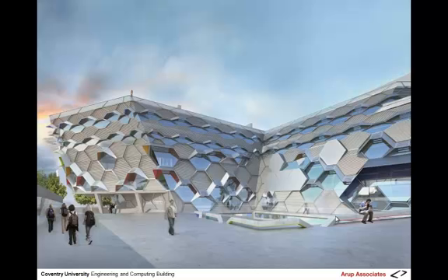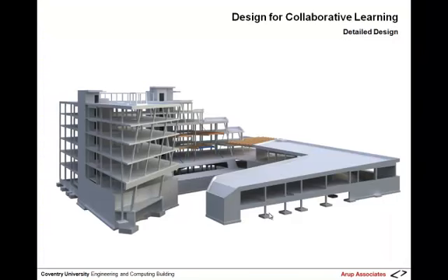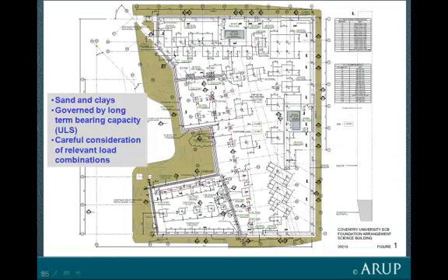But on the other hand, pad foundations for design at Coventry University, you can see the pads, it's all on shallow foundations here, shallow spread foundations. This was founded on sands and clays, interbedded sand and clays, and found to be governed by the long-term bearing capacity in the ultimate limit state.